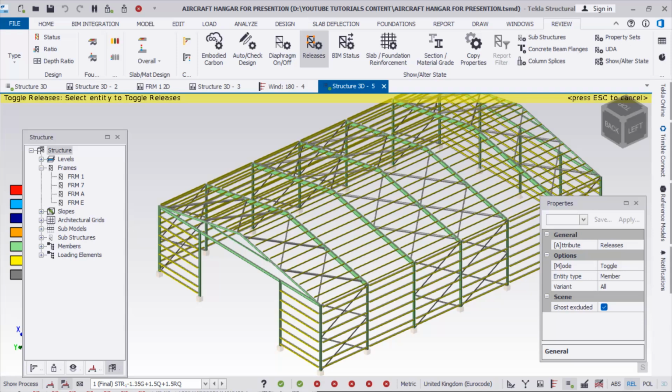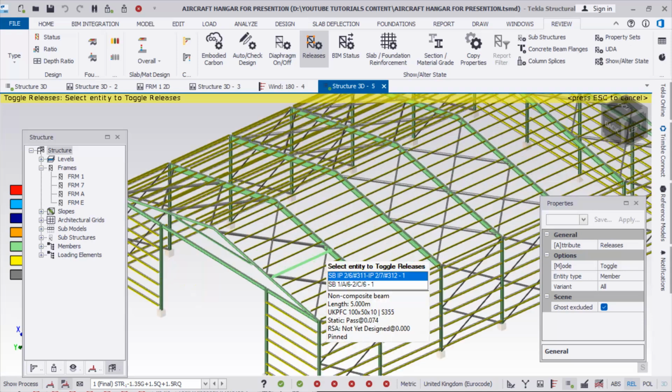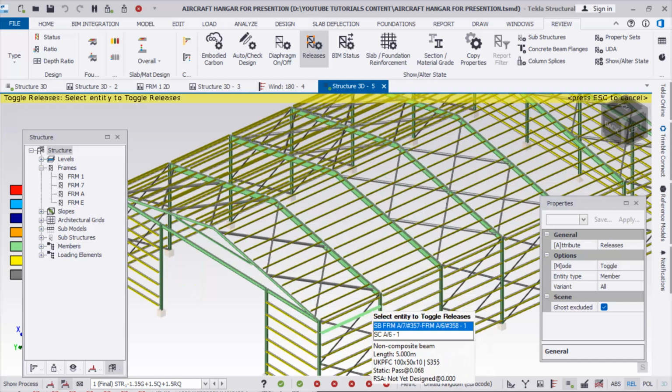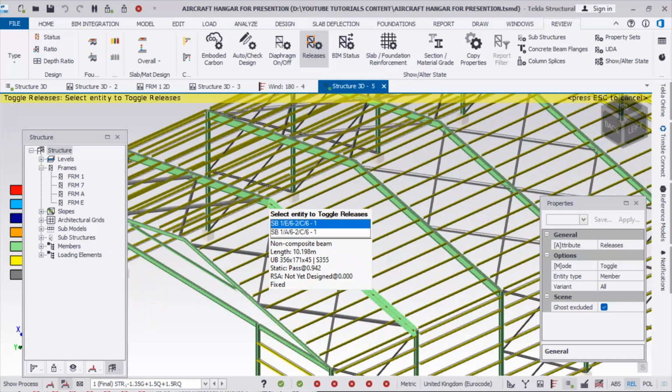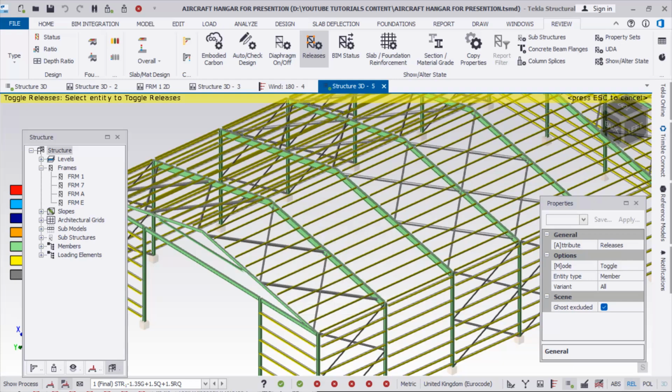So in this case, what makes the section deep is when the span is long, because in that case, it is likely to fail through deflection and bending, and you can only resolve that by increasing the section size. So that tells you that you should always give priority to the longer spans. And in this case, if you look at this rafter here, it is about 10 meters.